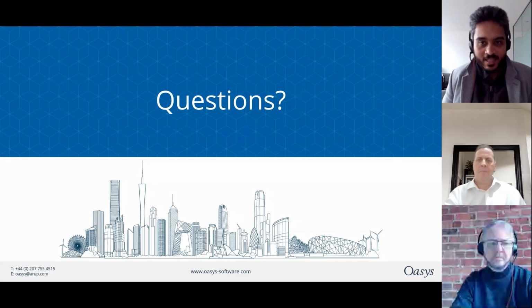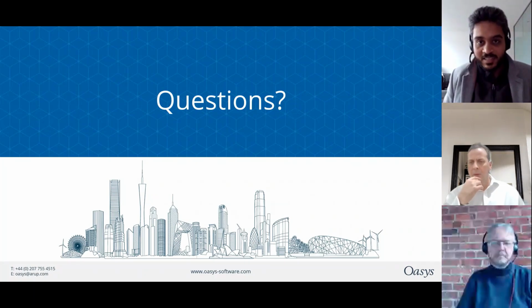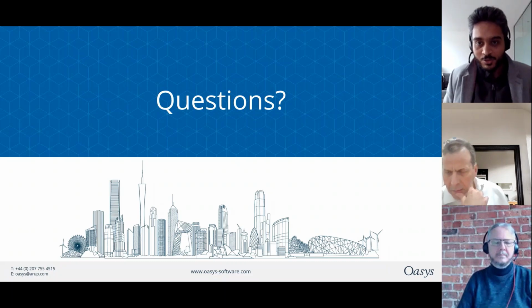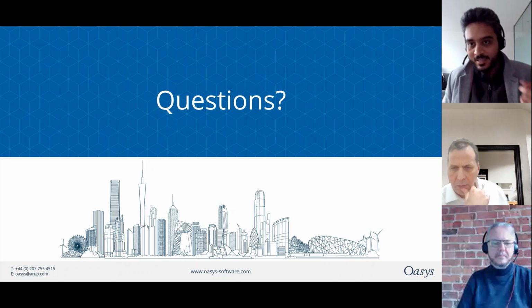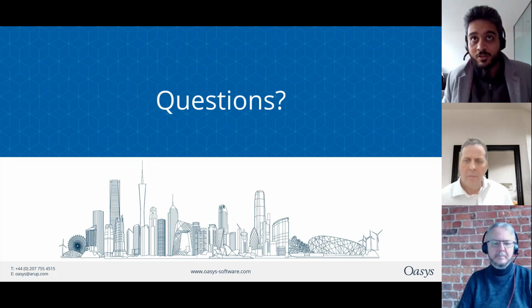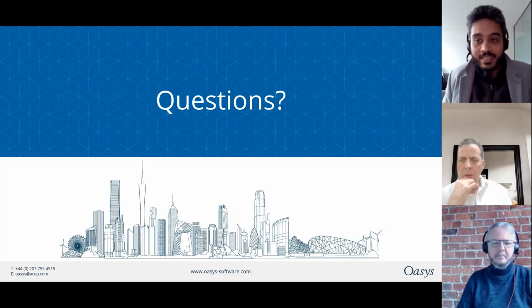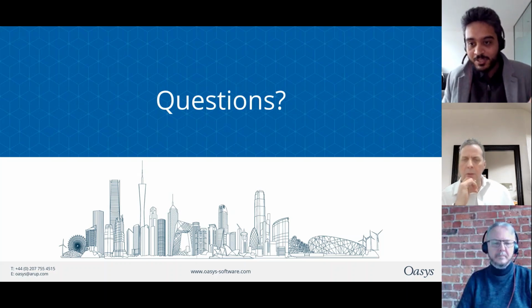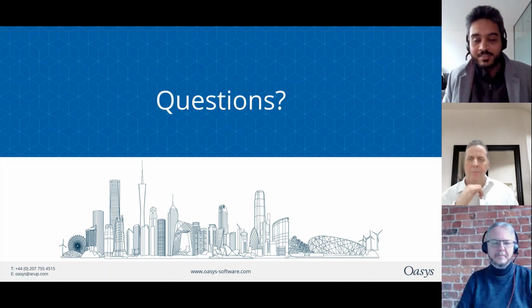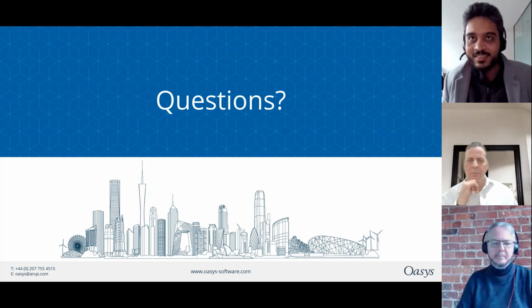Just type package manager in Rhino and search for the GSA Grasshopper plugin there. Make sure to check the include pre-releases box, and you should see the plugin in the dialog box there where you can download it from. What I'll do now is drop a quick link in the chat which shows how to do this exactly, so that you have a visual reference.